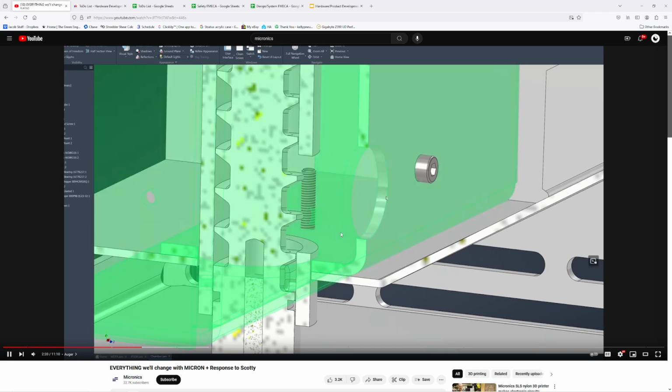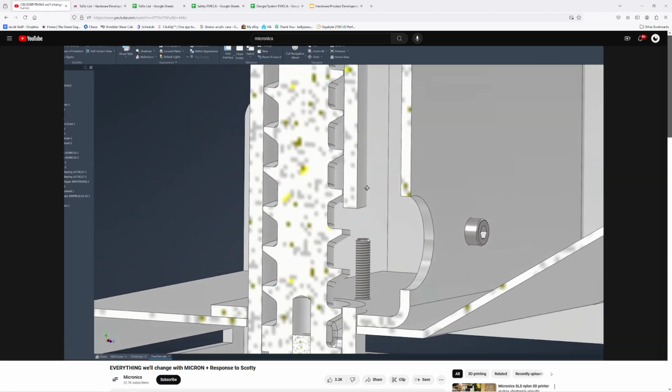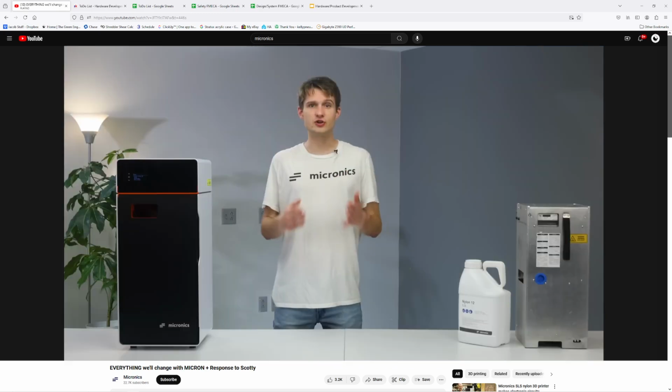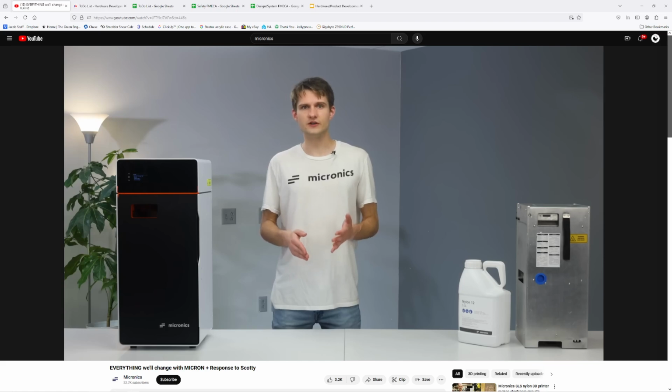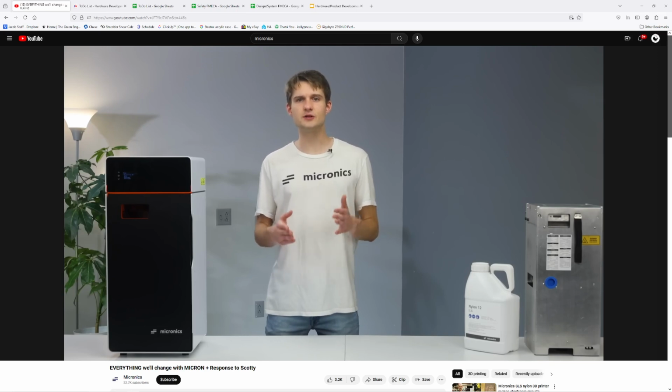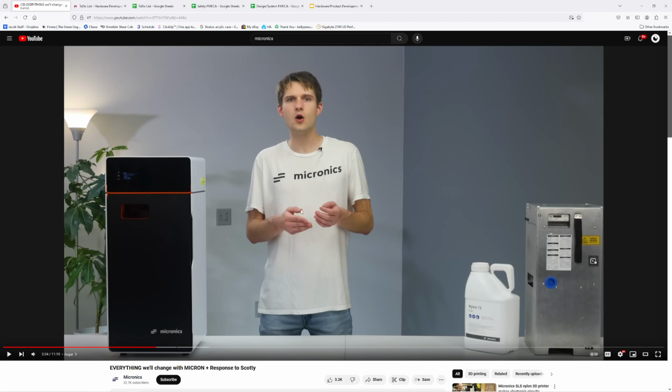All these things. This caused the powder to be lifted faster than it could be replenished. After addressing this, we kept the original auger configuration as it performed well in our tests. Nonetheless, we didn't foresee how shipping impacts could affect the printer, and indeed... So I can't really tell what he meant by that before. Like, you reverted back to the original design that jammed. That's basically what it sounds like. So it sounds like both versions didn't work well. So it sounds like what he did is he went back to the original design that had tight tolerances and opened the inlet hole.